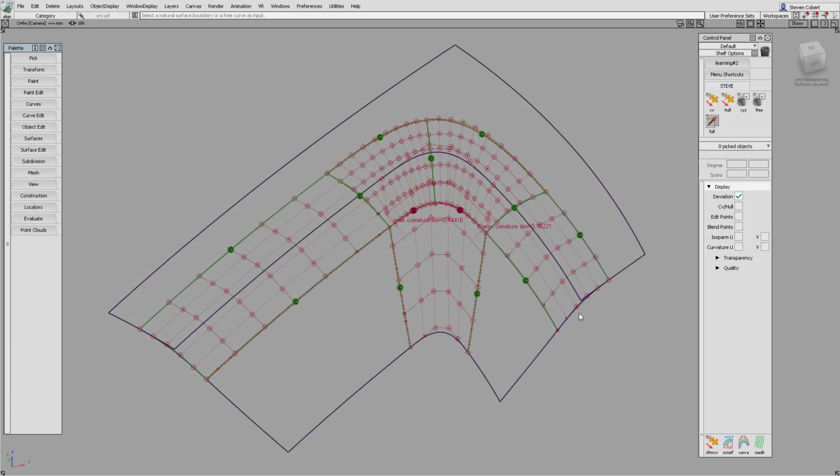Let's look at a real world example. So here we're trying to achieve curvature continuity on all of the edges, but you can see there's a couple of edges there where we haven't managed to do that. Now it may be possible with some more work to achieve that, maybe splitting up these surfaces into 3 rather than 2, maybe increasing the degree or the number of spans, but they're not very desirable results. With A-class work, as I've said before, we always want simplicity. So ideally, we'd want a surface in that corner which is degree 5 by 5 rather than having 2 higher degree surfaces.